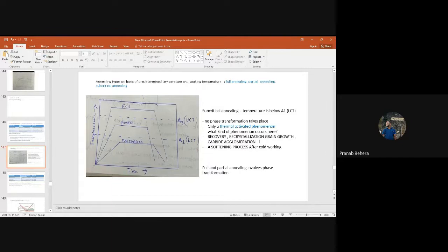Stress concentration. When you are applying load on the material, the load should be uniformly distributed everywhere, right? But the problem is what? At a particular edge of the needles, or at the corner of the needle shape carbides, the concentration of stress is high. That is a stress riser. And once there is a stress riser, a crack will initiate from there only. That is the crack initiation site.